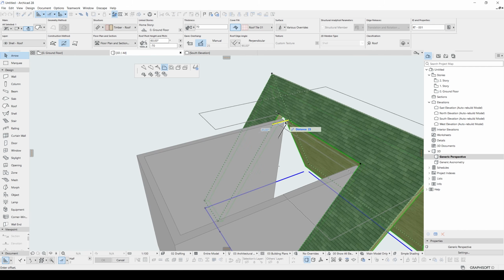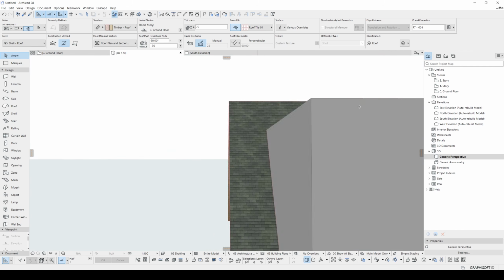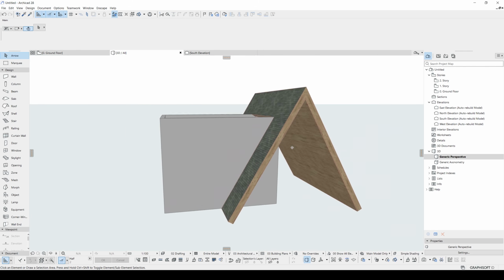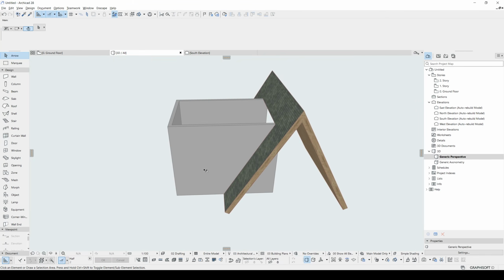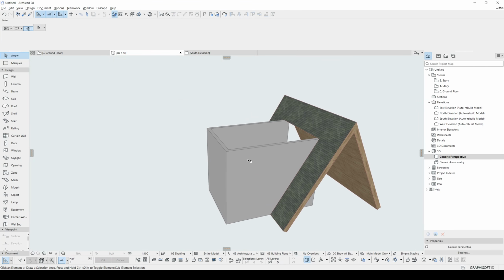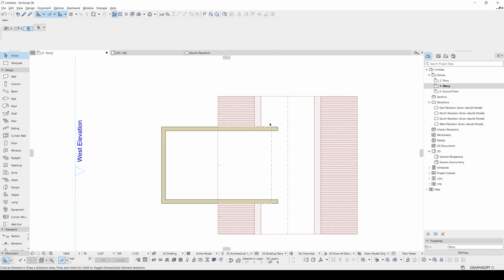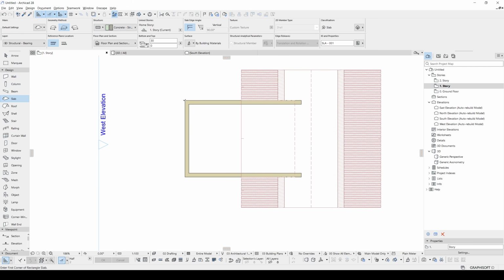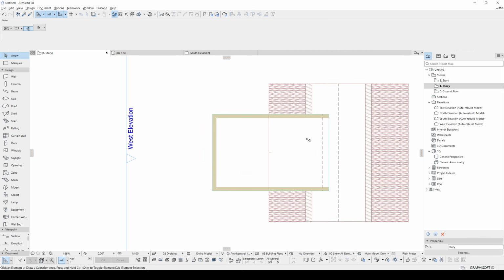It touches the wall, the corner, and the top. Something like this. Let's create some slabs. For the first slab, I want to make a balcony for the building. Let's go to the first story and click the slab, simple structure, and for the geometry, let's use this rectangular and make a rectangle like this.